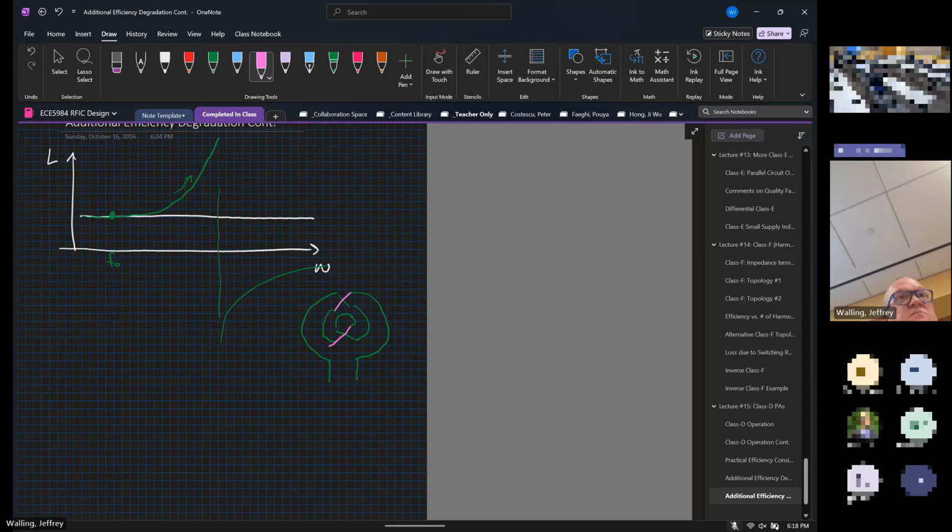The reason you don't see them do the center tap on another metal layer in the kit is that they just didn't want to draw a PCell that would do that. They can do it. If you want to do that, you can draw anything that you want to. But as you get closer to the substrate, the metals get thinner, losses get higher, and parasitic capacitance gets worse. Not necessarily a good thing.